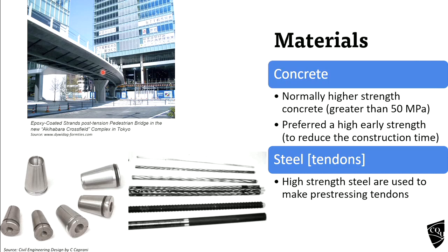Normally to get the full strength we need to wait 28 days, but normally the construction will go ahead after 7 or 10 days, because the concrete strength will increase over time. Within the first 7 days, it will reach around 65% in normal RC concrete. After 7 days, you can expect around 65% of the full strength.